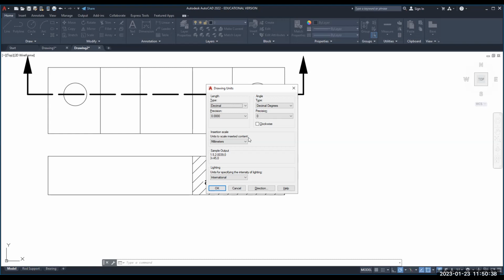Yeah, it's good to know. No way to do it. What you can actually do is scale your drawing. If you draw something in US and you want it in millimeters, you got to scale it by 25.4, smaller, but it's still going to be in inches. When you go to dimension it, it's going to dimension it really small in inches. What I would do is scale it, copy it, and then move it into a metric drawing. And then it would be metric. We'll actually talk about how to do that when we get there. But for now, just try to remember, start in ISO if you're metric.